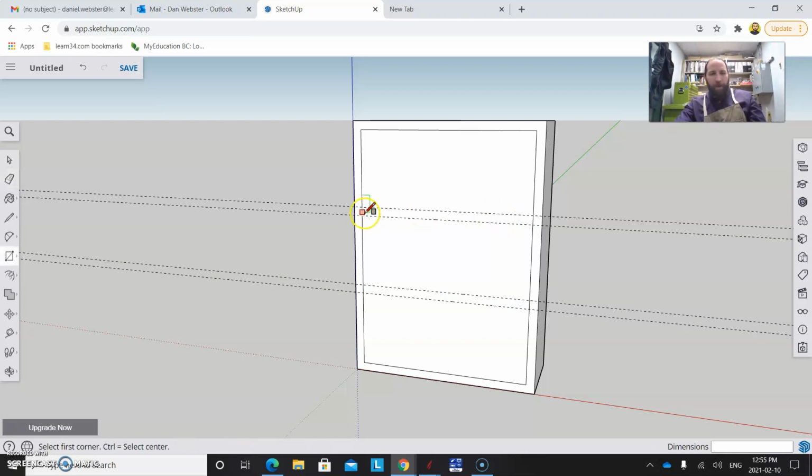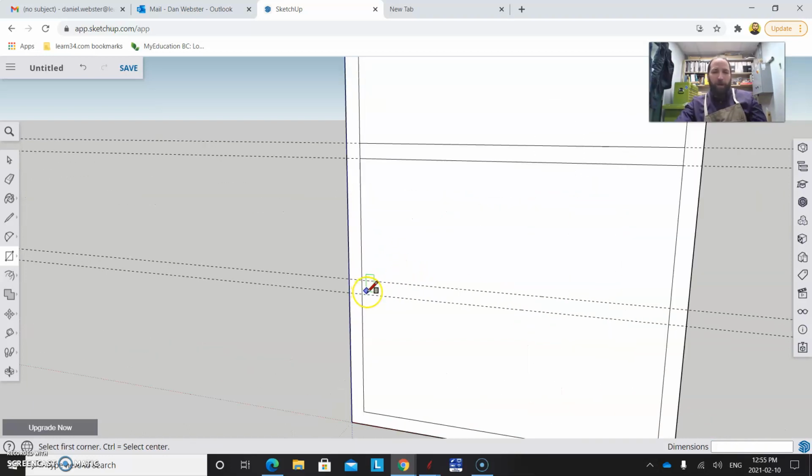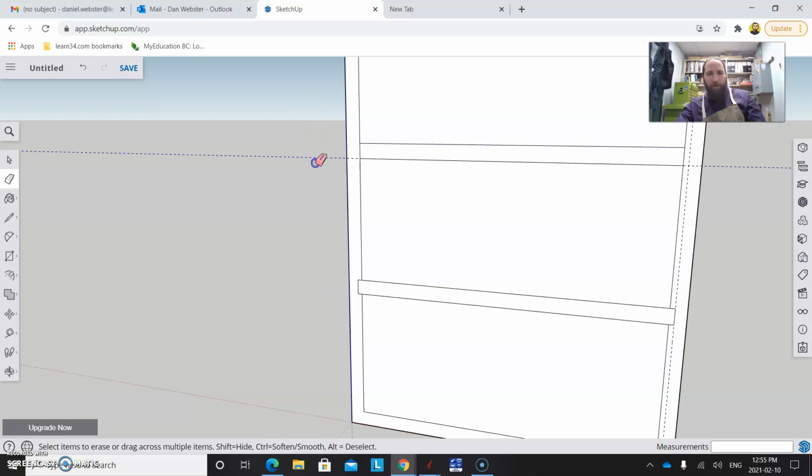I'm going to put rectangles in here. It's okay, I can put rectangles in just like that. What I'm doing is basically building shelves. I'm also, on this one, going to show you dados. So I'm putting a guideline in each direction by 6 millimeters. I make sure that goes on the blue so that when I draw this and then erase these 2 little stubs, it makes it look like I've got dados. So instead of modeling the whole piece, it just looks like they're there.